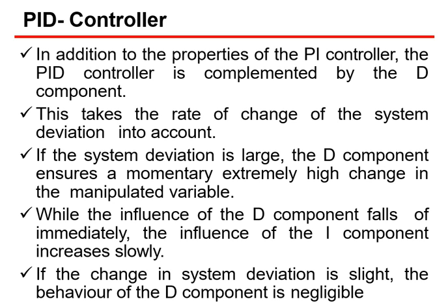Okay, but the design will be somewhat complex due to the addition of the three types of terms. So in addition to the properties of a PI controller, the PID controller is complemented by the D component. Whatever the disadvantages in the PI will be removed by this PID controller.